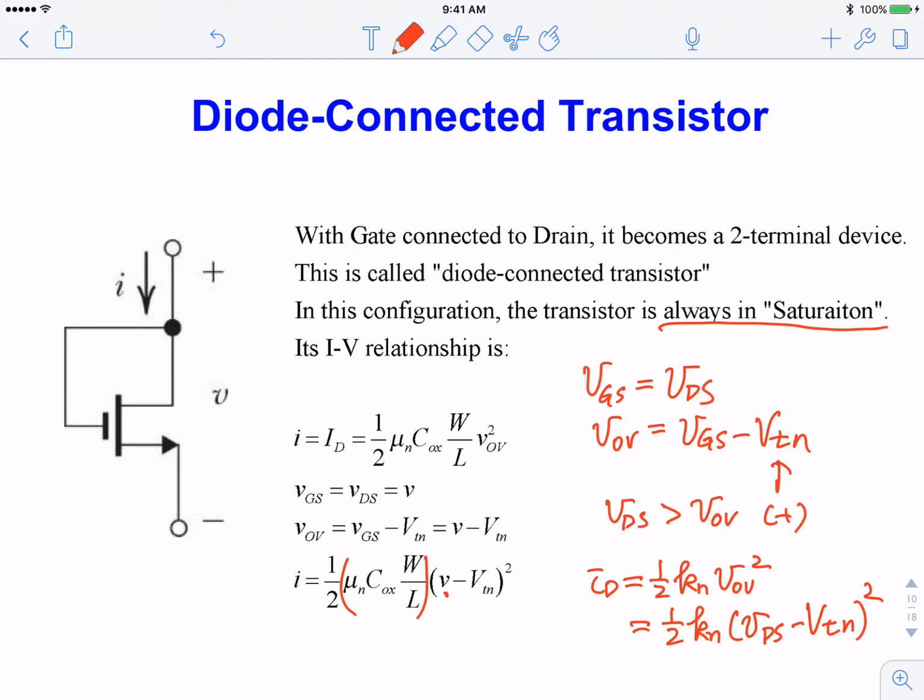But in ICs, even though the MOS transistor looks more complicated than a PN junction, it has multiple PN junctions in there, it is the simplest and smallest unit that you can use. So anytime you can use a transistor instead of a resistor, it is actually preferable, in terms of chip area, and usually translates to better power consumption. Okay?